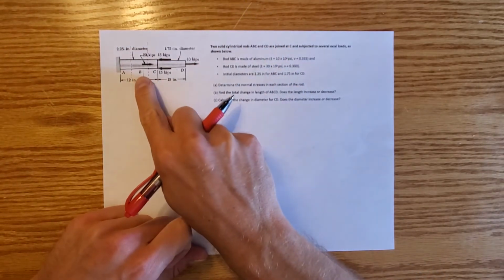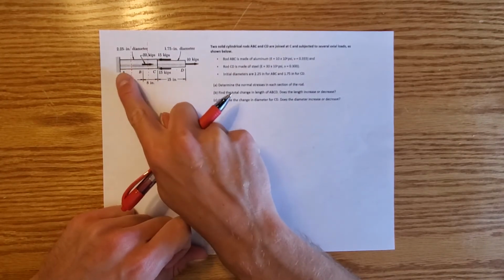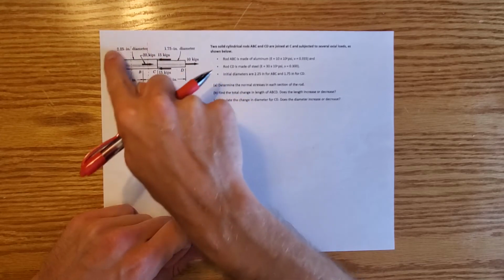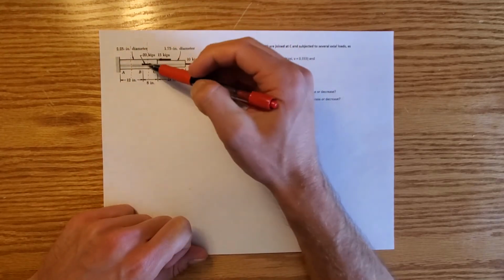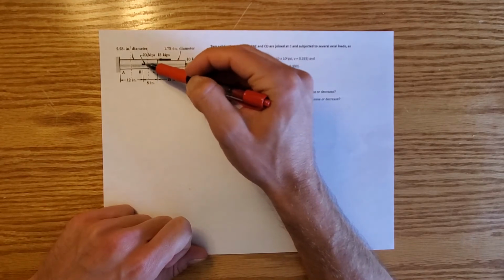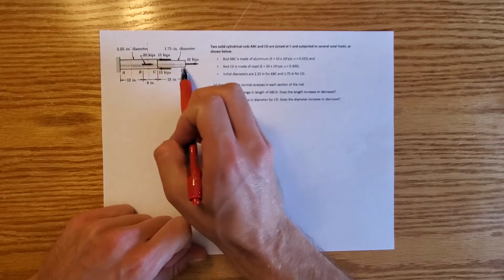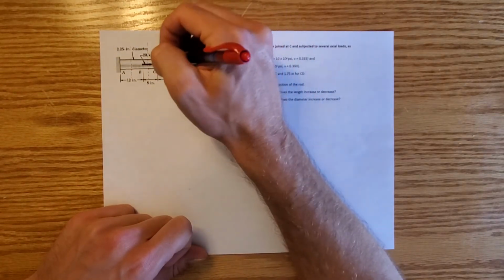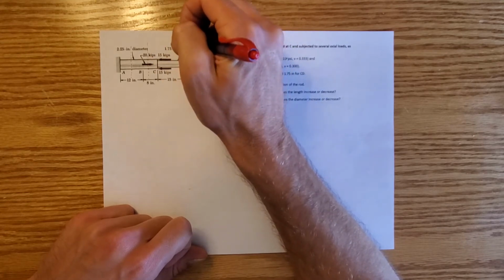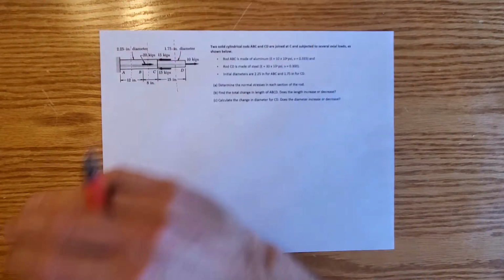And even if this letter B hadn't been here, we would still make this cut here because we can tell that section AB and BC, although it's the same rod, is going to experience different forces because there's this internal force going right there. So we draw one through BC. We kind of look from C to D. There's no internal forces here, but we do have 2 letters, and there's different end conditions. So we'll draw one more dotted red line to indicate a cut at that section right there.